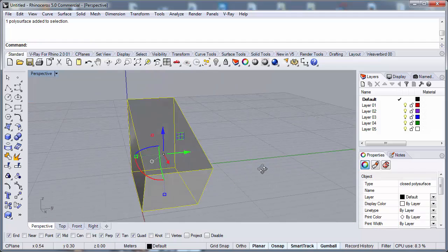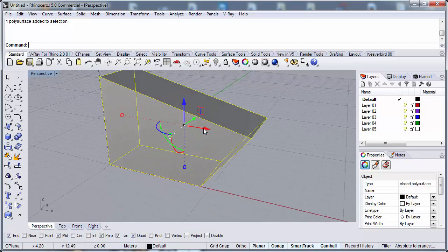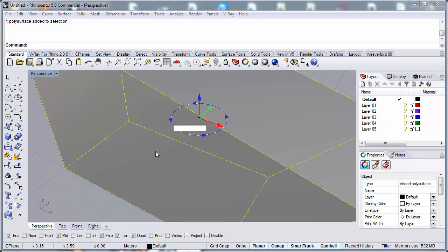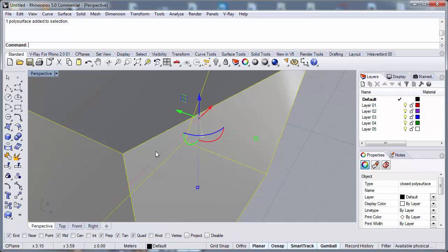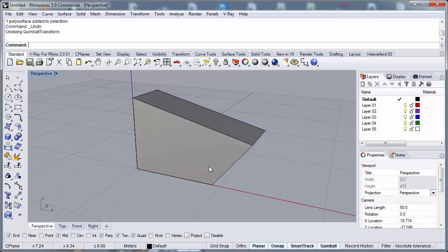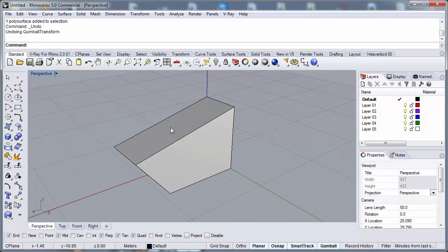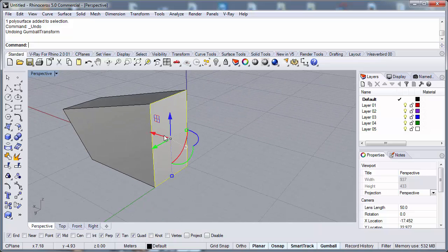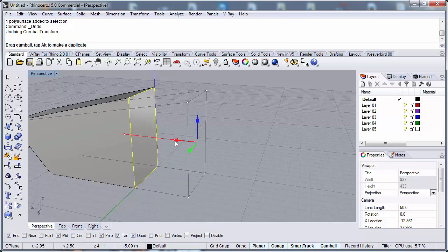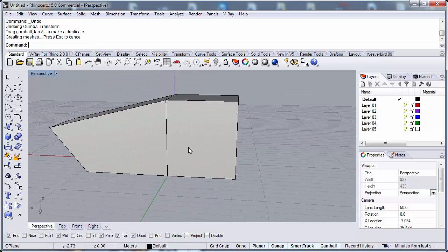And as we clicked on an axis and gave a distance, we can click on the rotation axis and give an angle in degrees. You see it rotated 90 degrees around the z-axis. And we can also get some more advanced stuff. If I start to drag this edge and keep down the control button, you can see that I can extrude this face.